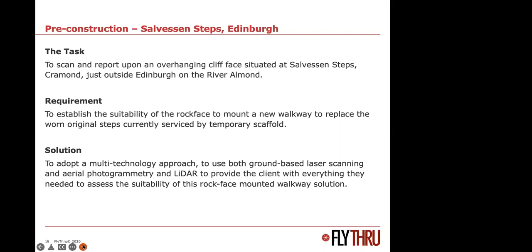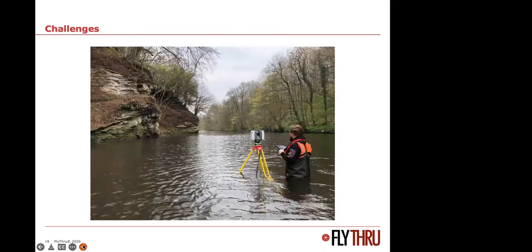So we were working with surveyors, complementing their laser scanning and creating a 3-dimensional image of the area of land that they wanted to develop. So the week before this, we couldn't have actually gone in the river, but at this time we took 2 days doing laser scanning of the rock face you can see in the picture, simply moving the laser scanner down the center of the river and taking the necessary image in 3D.